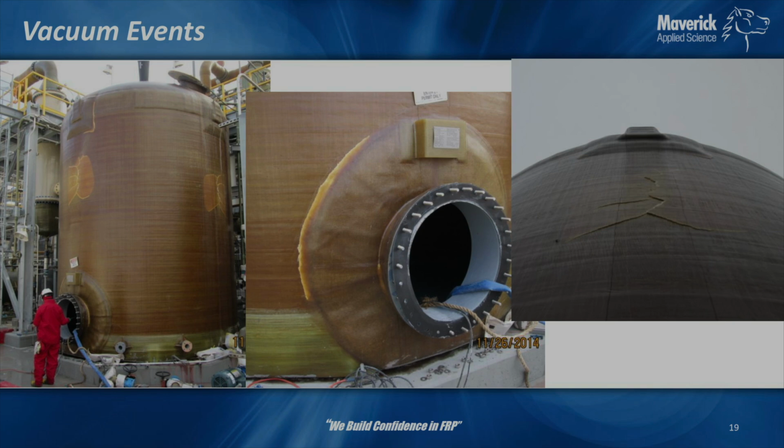These are like through wall cracks here. What we see like up here where you have these hard points, where you have these thicker points, where this might be a lifting lug or something like that. So that's like a block on the shell, and it wants to keep that round, but the shell wants to do something different. Starts to want to peel that away. This is a look at the manway, it'd be probably the other side of the manway there, where this was flexing so much, basically that big thick laminate just got peeled off the wall there.